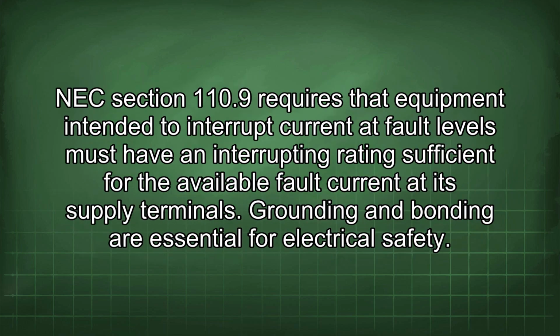NEC Section 110.9 requires that equipment intended to interrupt current at fault levels must have an interrupting rating sufficient for the available fault current at its supply terminals.